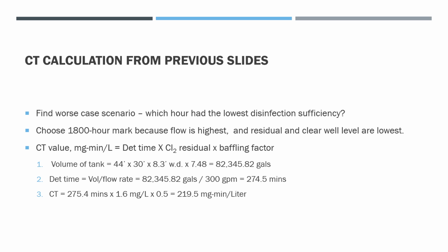Typically on Lake Erie, you would need about 8 to 10 milligram minutes per liter in the summertime and maybe about 70 or 80 milligram minutes per liter in the wintertime. They have way more than is necessary here.